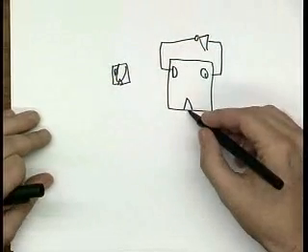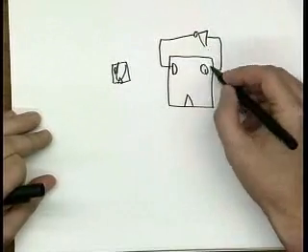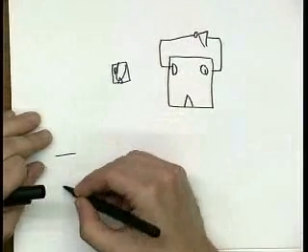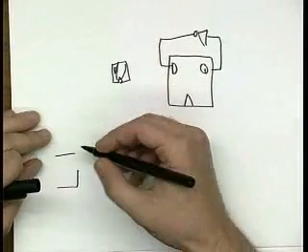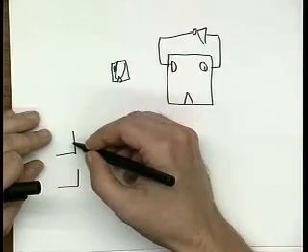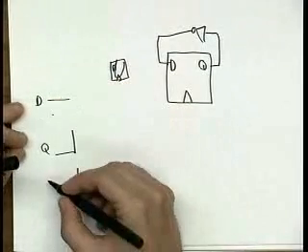Every time you get a rising edge on the clock, it takes the input and feeds it to the output. Did I get that right? Yeah. And since that's inverted, say I started with a 0 on D, my clock comes in, that's my LO, right? The Q transitions, D is high, Q goes high, Q, D, clock.